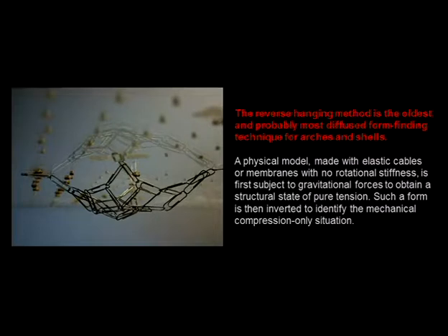Of course, you need to be a little bit more precise than that. This is a little bit imprecise. But if you do the model properly, you can simulate with a physical model a structural property. You can't do a model just using this. You need to connect this one with another one, making sure that there is no rotational stiffness, so that the elements are able to rotate. In that case, you get the state of pure tension.